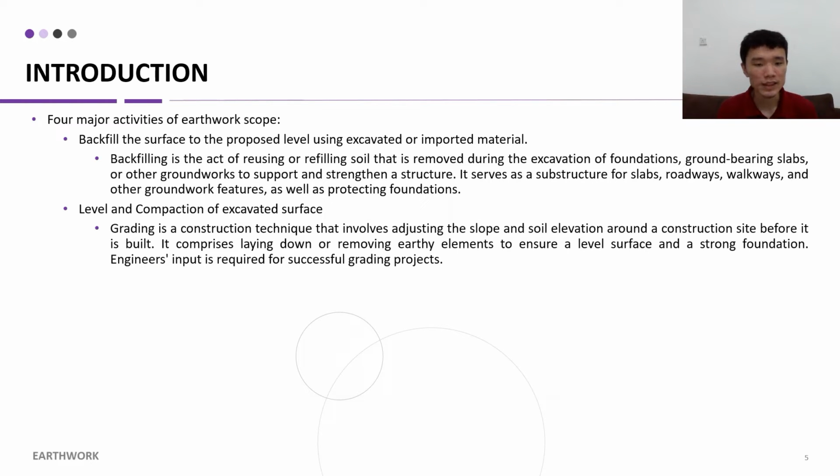Next activity is backfill the surface to the proposed level using the excavated or imported material. Backfilling is the act of reusing or refilling soil removed during excavation of foundations, subsoils, or other foundation works to support and strengthen structures. It serves as the base structure for floors, roads, sidewalks, and other infrastructures, as well as protecting foundations. Last but not least, level and compaction of excavated surface goes on.